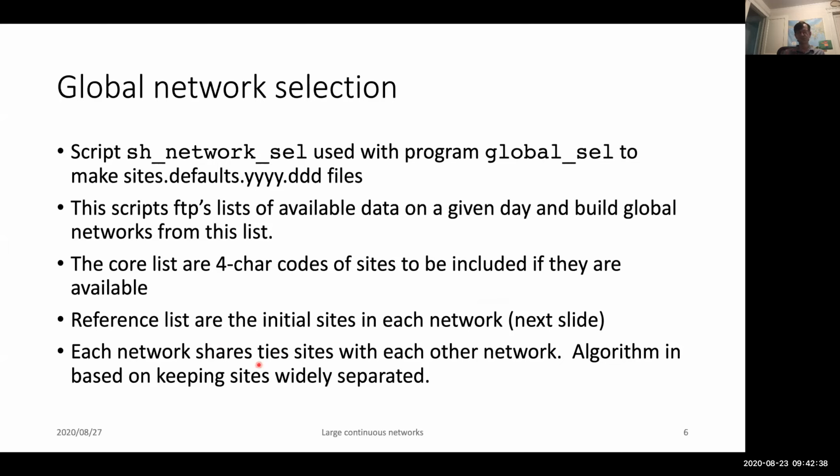There are some interesting aspects if you want to look at how we form double differences and the uniqueness of double differences. When you use a full variance covariance matrix, you can show that it's close to rigorous. Even though these single sites are used twice, because of the way the double differences tend to be formed, you're not really overusing data when you do this.